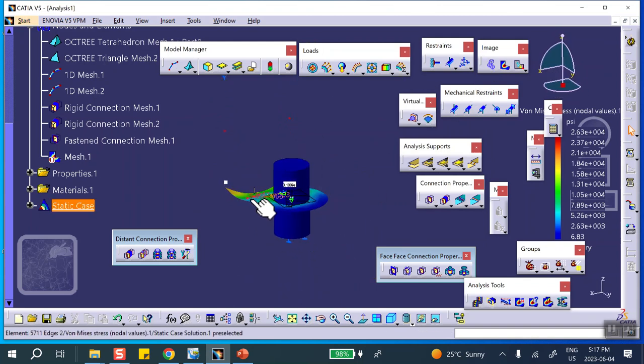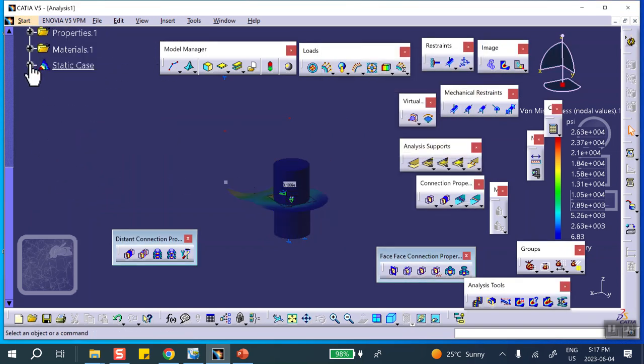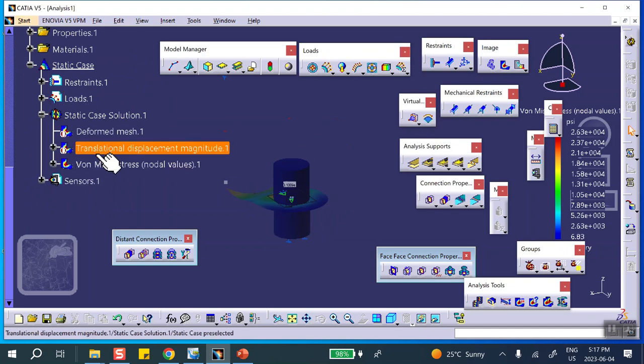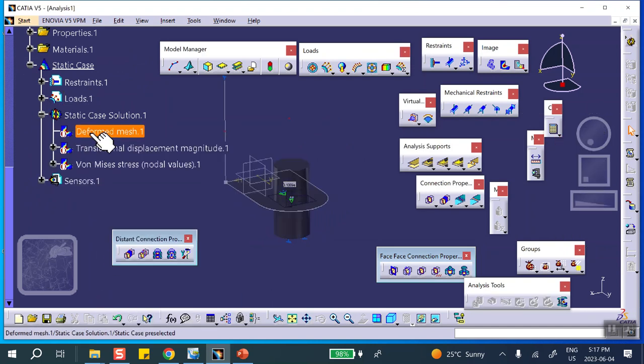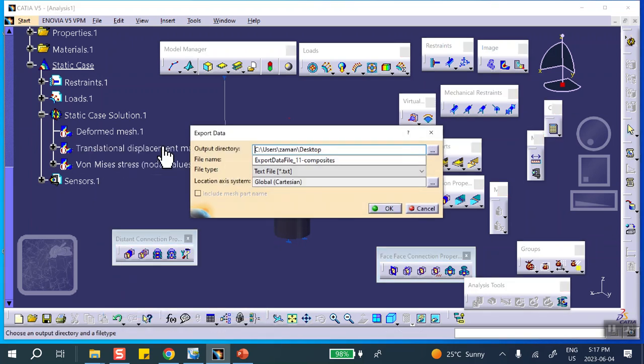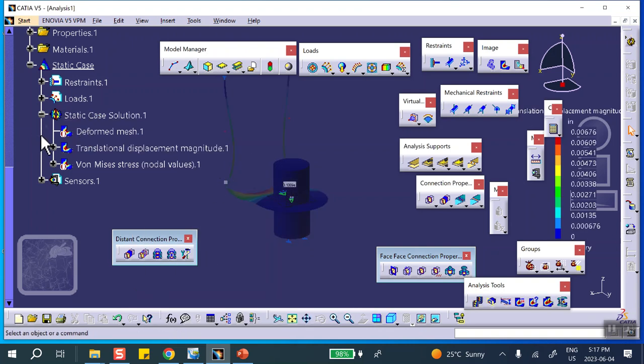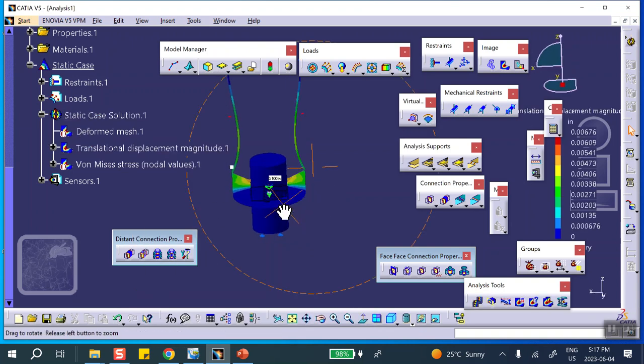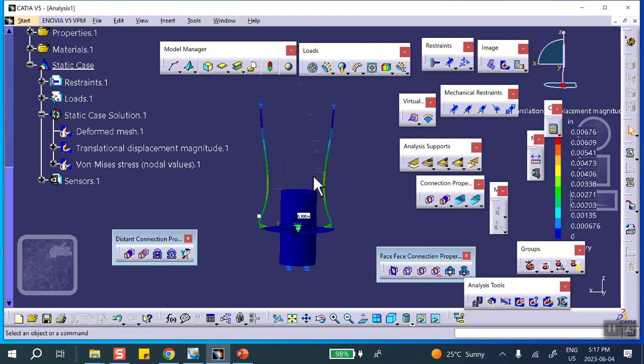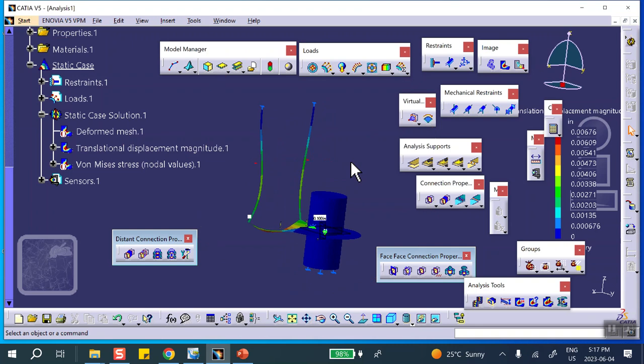But the thing is this. Let's go back here. Cancel that. Let me go back to a displacement instead of von Mises. So deactivate this, activate that, because I want to ask you something. Okay, you might say, if you look at the front view, you see there's a symmetry right there. But then you might say, wait a minute, this can't be a cable. And you're absolutely right. Because they are welded at this location, they don't act as a cable.